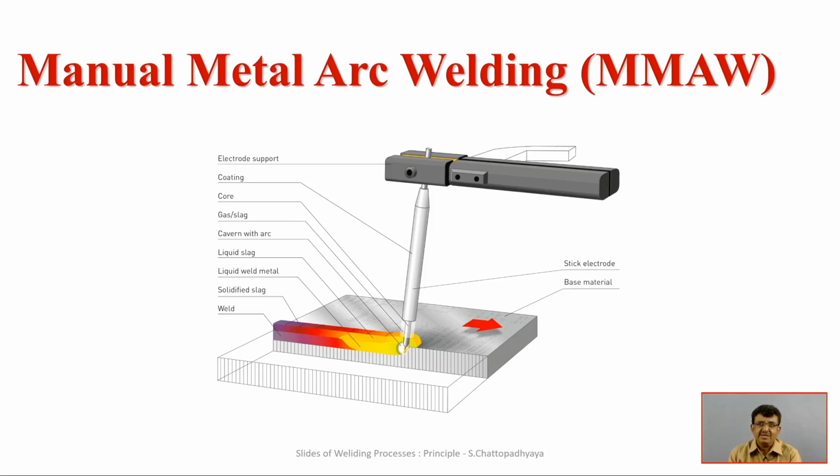The advantage is that oxides will not be formed, then the weld's homogeneity, quality and strength will be great, and that was a terrific discovery. After this discovery of the oxidization prevention strategy, welding became successful. And so successful, the beauty of arc welding is that if it is done properly, then the strength of the weld is more than that of the parent metal, and that is terrific in terms of joining. If we have done it appropriately and put it into a tensile testing machine, then the joint will not break, the parent material will break, and that is the unique selling point of this welding process,